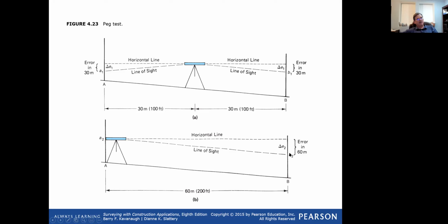When you turn now to look over here, whatever your error is going to be doubled. And this is the true error of your instrument, is half of this distance right there. This is a situation where you need to know what these elevations should be, A and B. Would be helpful, but otherwise you'll have a different answer. You should be seeing like this, whatever this number here is the same here, and you get twice the error.